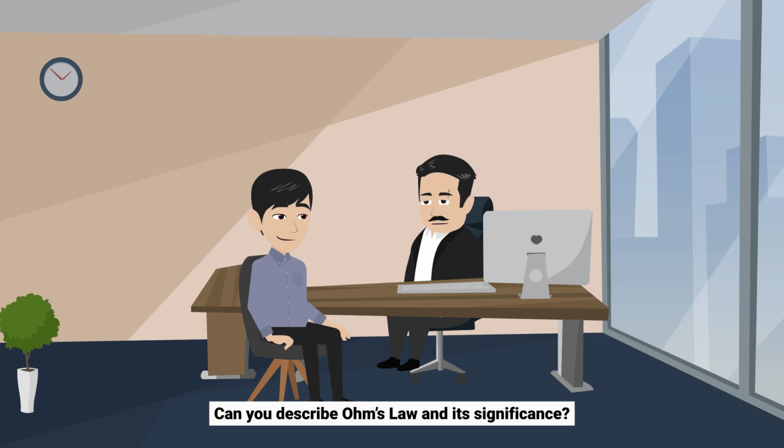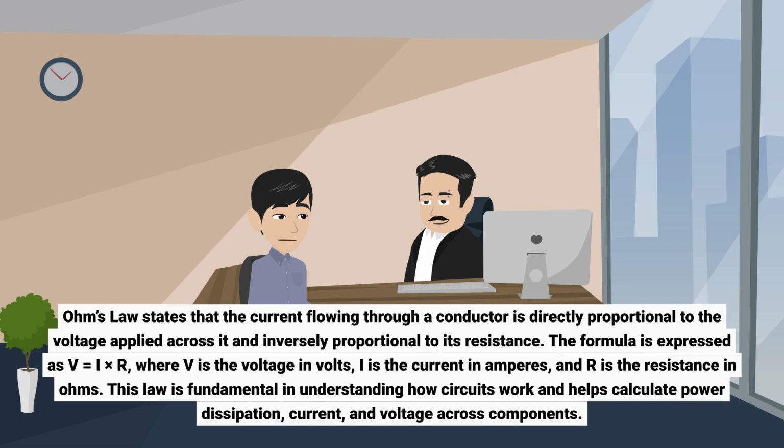Can you describe Ohm's law and its significance? Ohm's law states that the current flowing through a conductor is directly proportional to the voltage applied across it and inversely proportional to its resistance. The formula is expressed as V = I × R, where V is the voltage in volts, I is the current in amperes, and R is the resistance in ohms. This law is fundamental in understanding how circuits work and helps calculate power dissipation, current, and voltage across components.